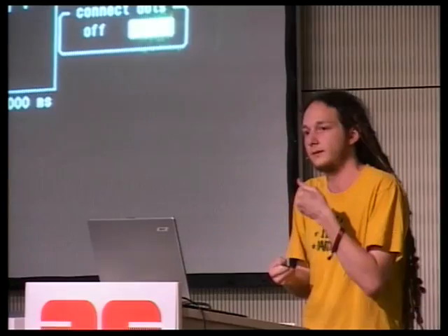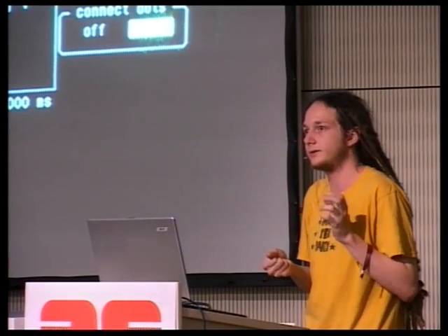Now, looking at a scope, you can see the timing. And once you initialize it, it's waiting for 0x80 to be sent across, because it needs to figure out the timing with which it's going to speak. And then you can view the conversation as bytes going across the wire between the 2 chips. And I'm going to refer to bytes as packets, because that's sort of how things work.